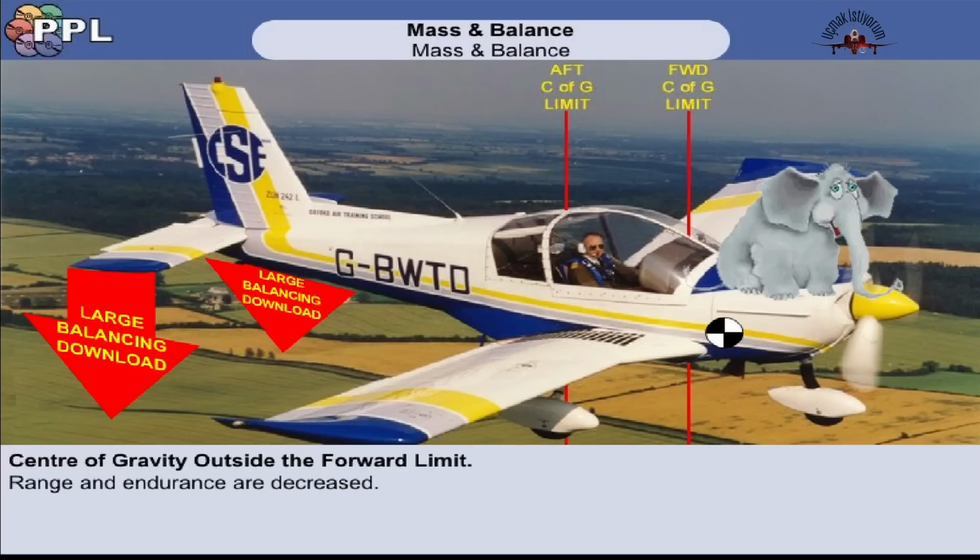Range and endurance are decreased due to the increased trim drag as the elevators must be used to trim the aircraft. The ability to apply nose-up pitch is decreased because the elevators, having been used to trim the aircraft straight and level, have less up range remaining.